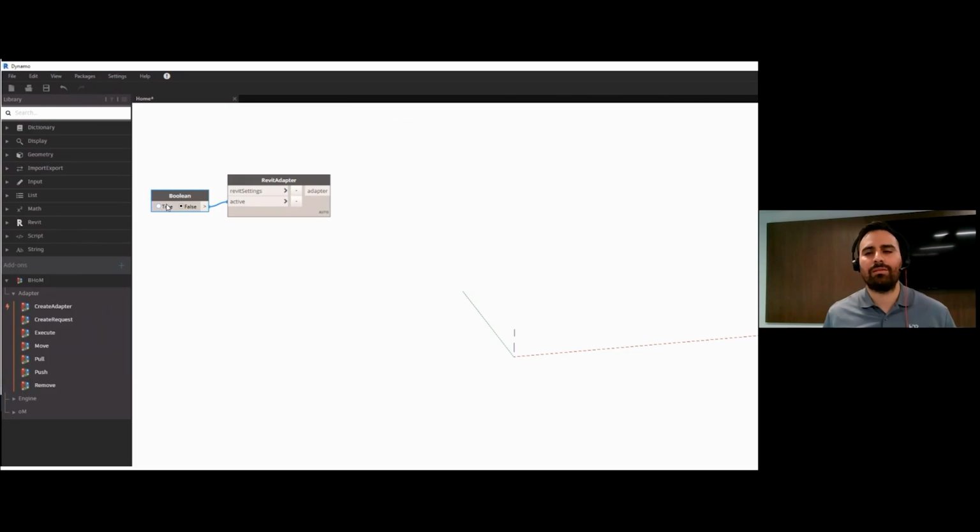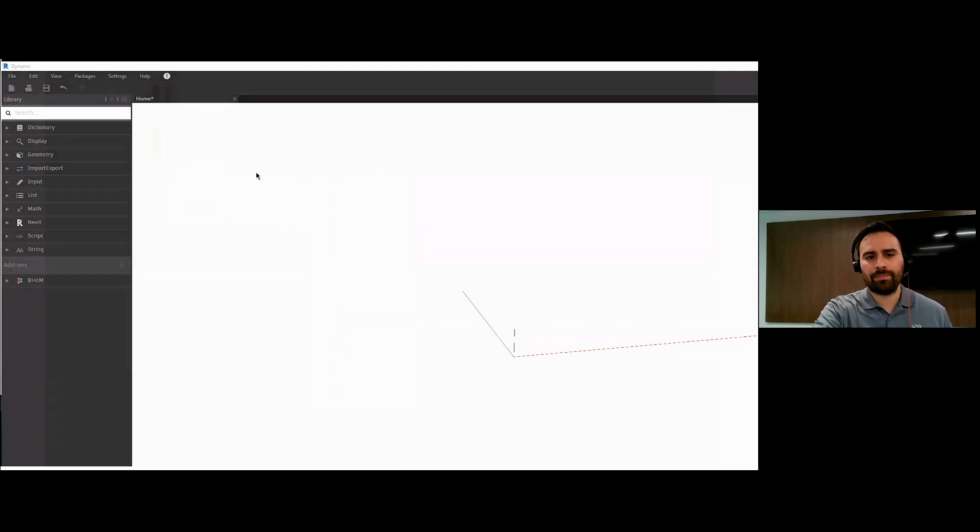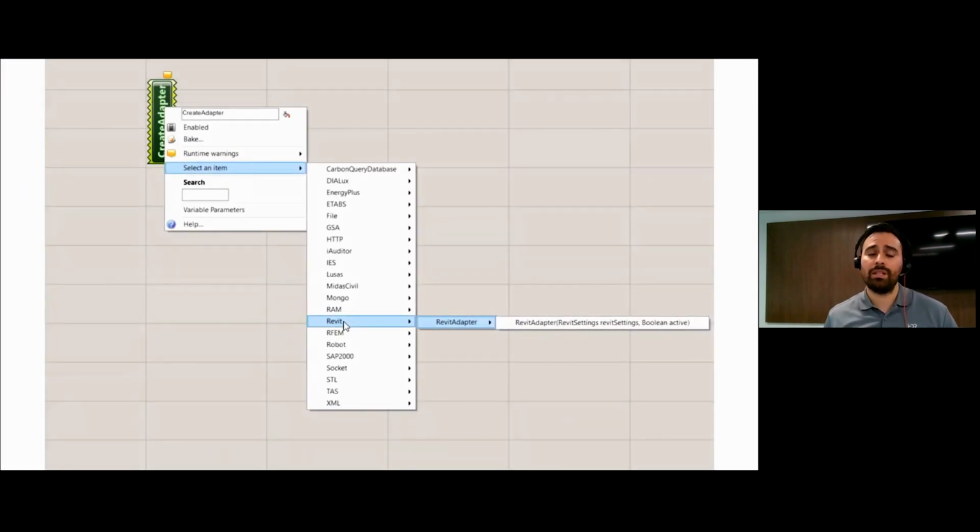And I would say, just a side note, when you're in Dynamo, I would run in manual. I would not run automatic, especially with running with BHoM, or really anytime you use Dynamo, you should be using manual. In Grasshopper, it's the same thing.